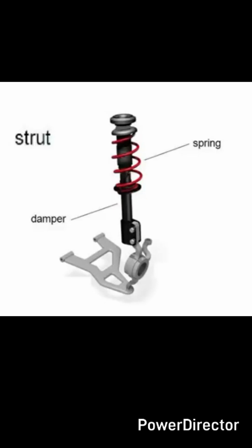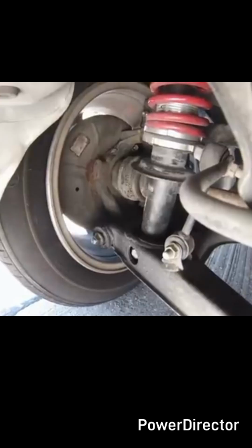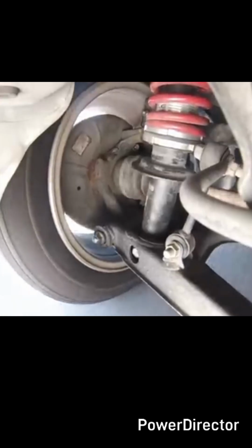When the vehicle comes in contact with the irregularities of the road, the wheel moves up and down on the radius of the lower link. Due to this motion, all the shock is transferred to the strut, which absorbs the maximum amount of force. It has a relatively simple construction, which results in a compact design, and is cheap.